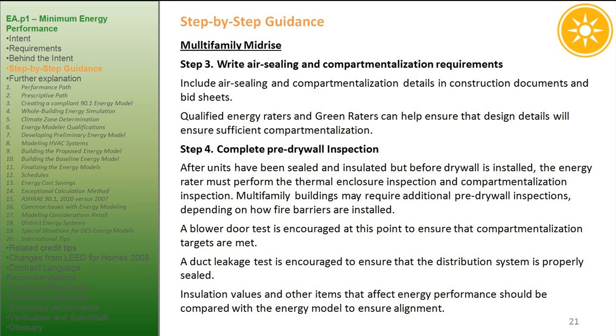Step 3. Write air sealing and compartmentalization requirements. Include air sealing and compartmentalization details in construction documents and bid sheets. Qualified energy raters and green raters can help ensure that design details will ensure sufficient compartmentalization.